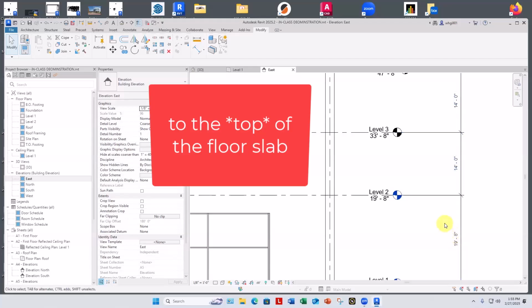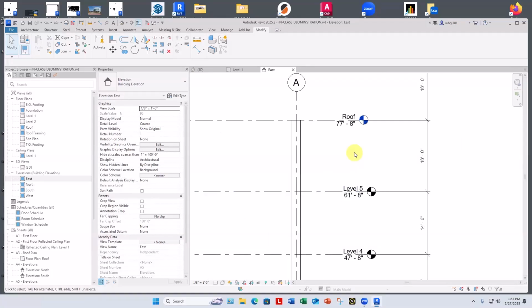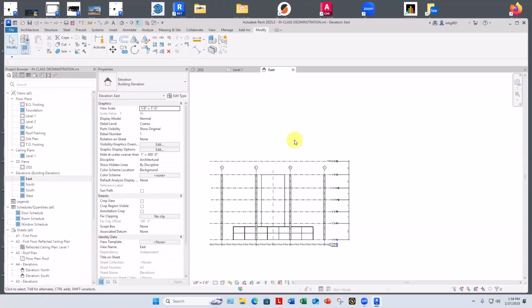19.8 to the floor, 15.8 to the top of these guys, but there's structure and stuff in here. These might not be exactly right, but if they end up being 4 inches more or 4 inches less, we'll be able to just move the level up and down and everything will go with it. It's pretty slick. Now that we've got our levels in, I would like to put the floors in.